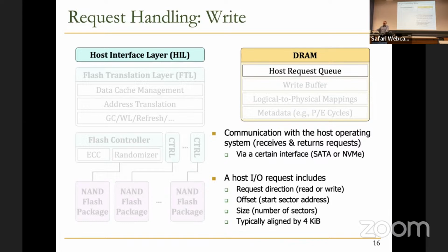So in that domain, you can think of having byte access to the flash. Flash memory doesn't have to provide page access granularity. It can also be sub-page. Yes, it has some overheads, of course, but basically it's a matter of trade-offs. So in that system, you can think of what the trade-offs are, how much performance you can get if you provide more fine-grained access to your flash memory, and what the overheads are, and then make a decision.